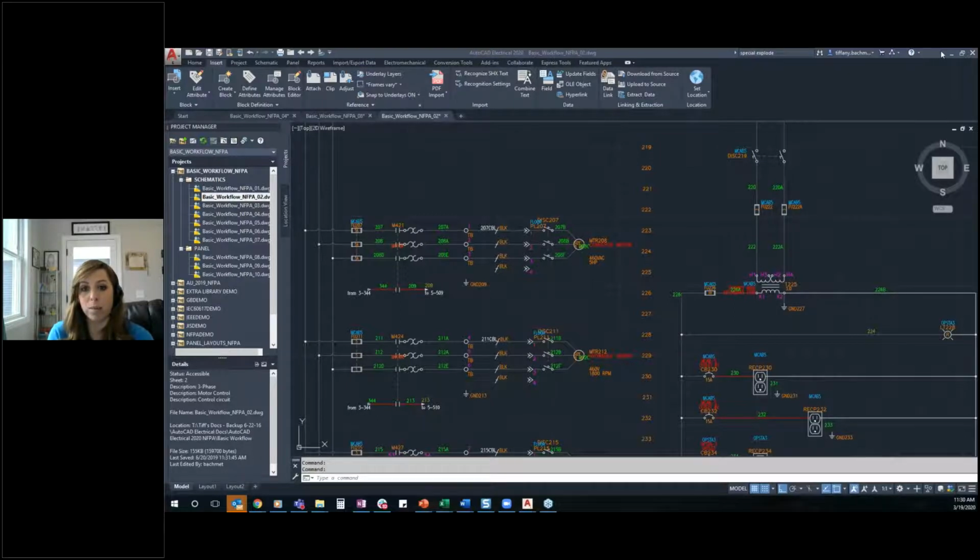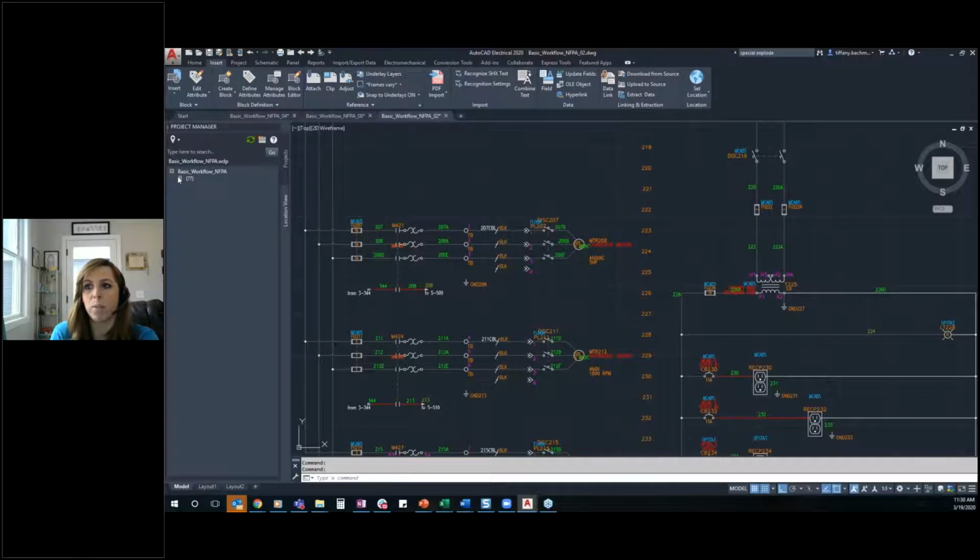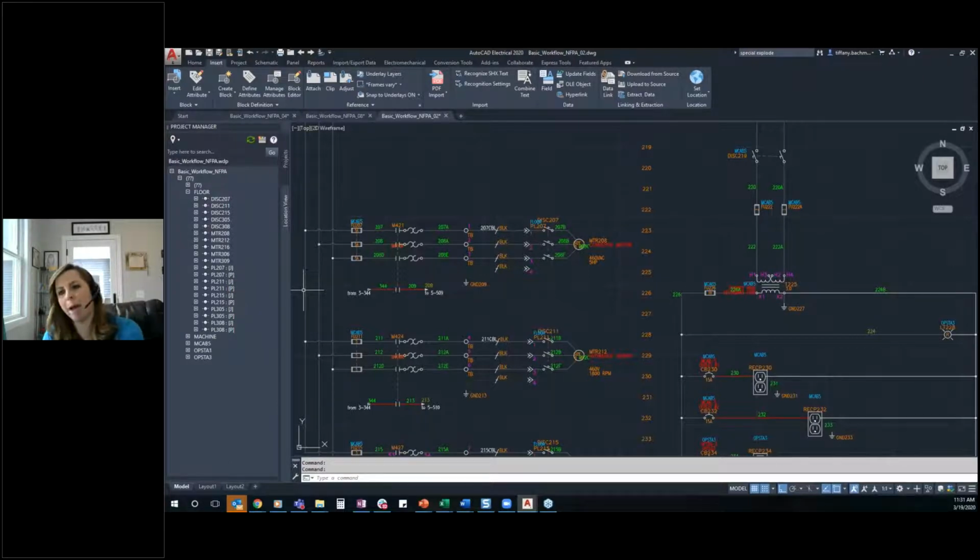We integrate directly with Inventor. The AutoCAD Electrical to Inventor workflow is called EMX, similar to what we often call the electromechanical workflow between Fusion and Eagle. And it's one-to-one, it works back and forth. The location view here on my screen allows me to connect this to Inventor to see what Inventor parts are already there. I don't have this one connected, but I can see what is already there. If I'm building this up in assembly form within Inventor, it'll come back into electrical and vice versa. So yes, we absolutely have that interoperability here as well, similar to what you're experiencing with Fusion 360 and Eagle.